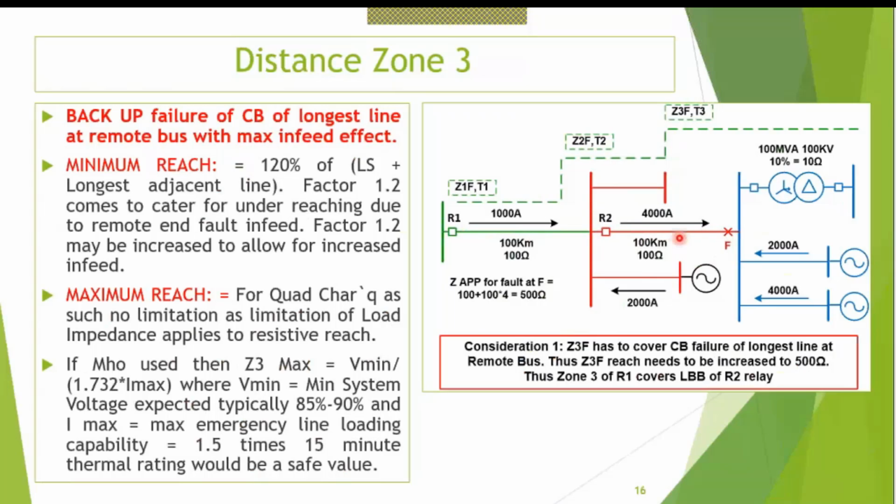promise to protect this line if the relay at the remote bus longest line does not operate. That is the philosophy of this zone 3. With maximum infeed effect, it will try to protect.